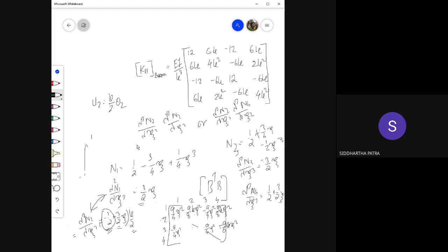Okay, but unlike whatever rule we imposed on our shape functions, for example the Kronecker delta rule, we couldn't do it here. We cannot say sigma Ni equals 1. No, this is not true. Actually N1 plus N3 equals 1 because these are both coefficients of your w1 and w2.